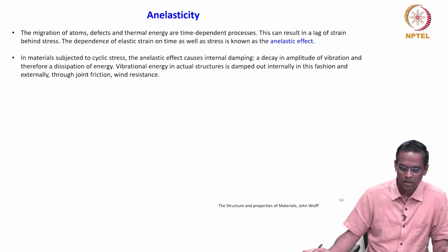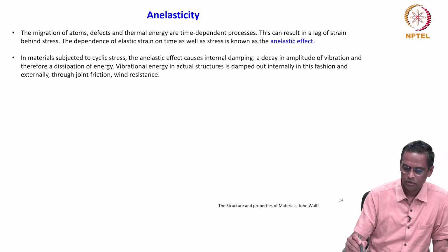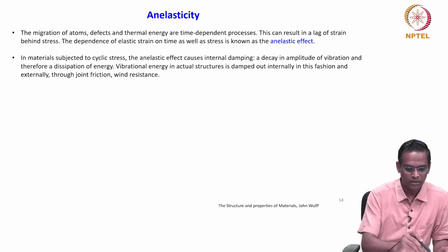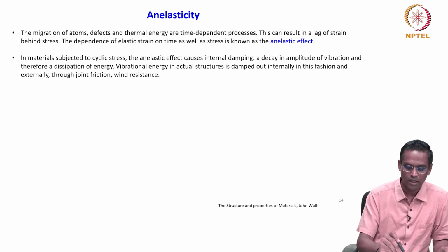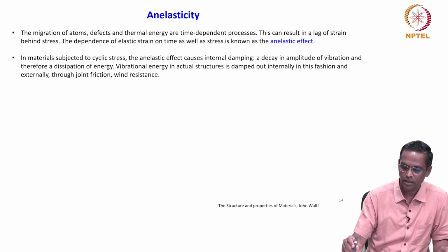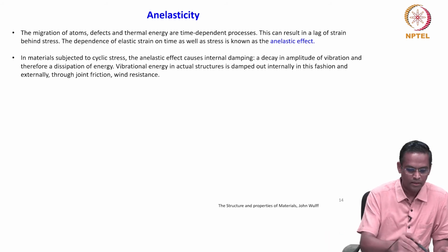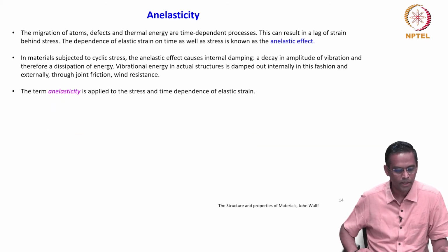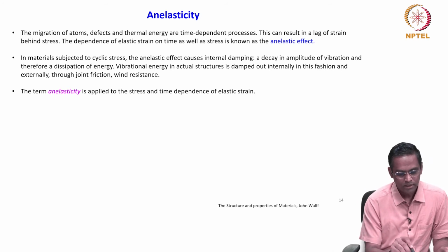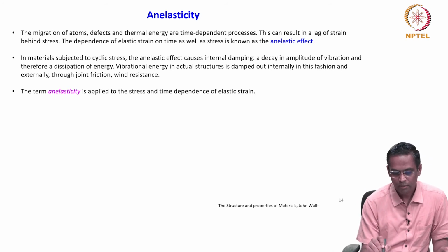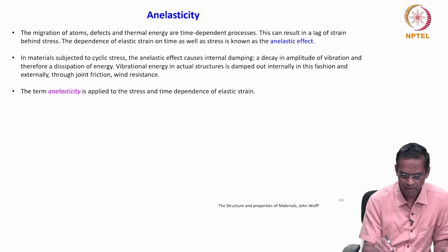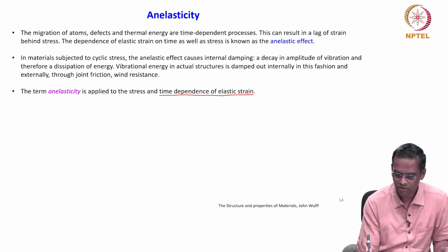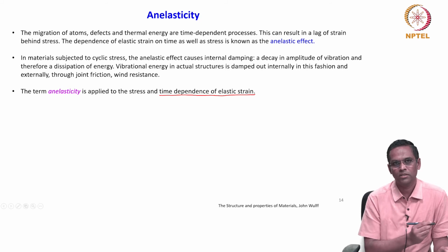Okay. So, that is internal damping, the decay in amplitude of vibration and therefore the dissipation of energy. Vibrational energy in actual structures is damped out internally in this fashion and then externally through joint friction, wind resistance and so on. Okay. So, the term anelasticity is applied to the stress and time dependence of elastic strain. So, time dependence of elastic strain is anelasticity.